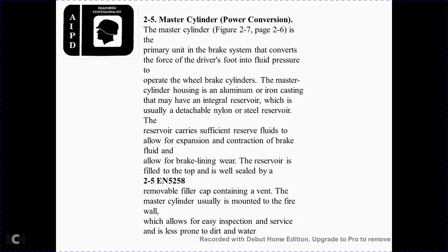The reservoir carries sufficient reserve fluid to allow for the expansion and contraction of the brake fluid and for brake lining wear. The reservoir is filled to the top and sealed with a removable filler cap. The master cylinder is easily mounted on the firewall, which allows easy inspection and keeps surfaces less prone to dirt and water.